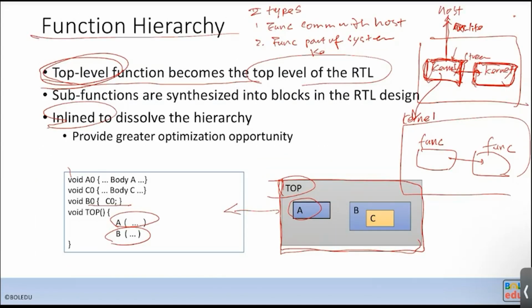However, for the interface between kernel and kernel, you have a few types. One is AXI-Stream. Basically, you use a stream interface between them. I think that's the most efficient way to interface kernel and kernel functions.